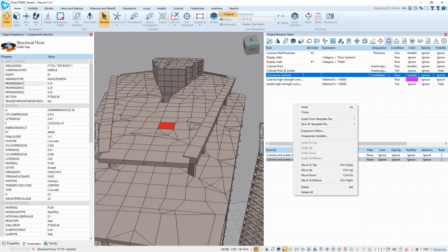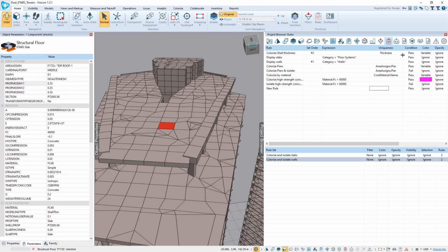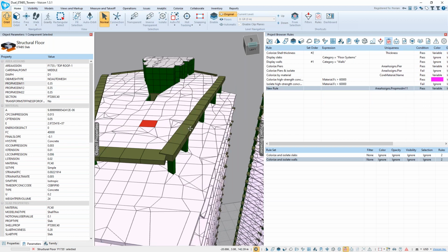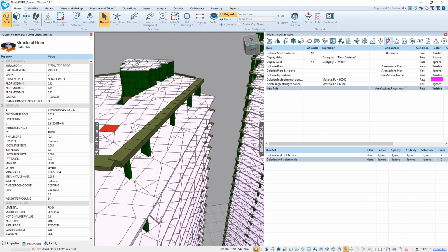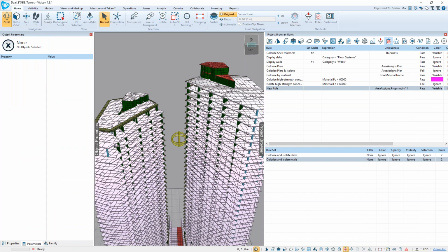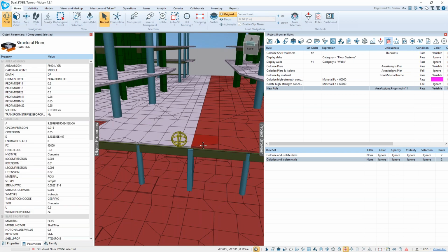I create a new rule, right? So I'm just going to insert a new rule. It's as simple as just entering that variable right here. So you see area assignment, property 11, and I zoom out and I see, wait a minute, something is strange, right? I can see white is where it's defined consistent. And here, either there were two separate people or the same engineer, I see there's a different assignment on the same, what should be a continuous slab with the same exact structural properties.